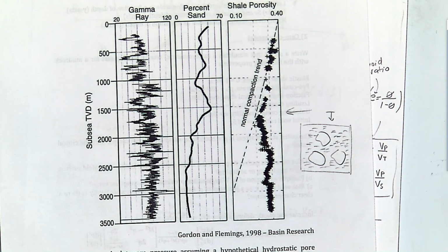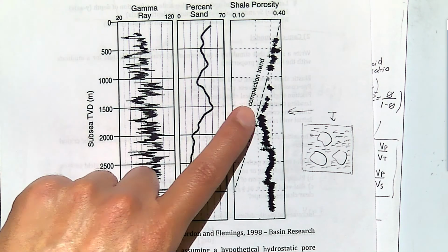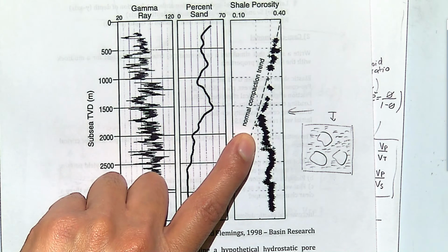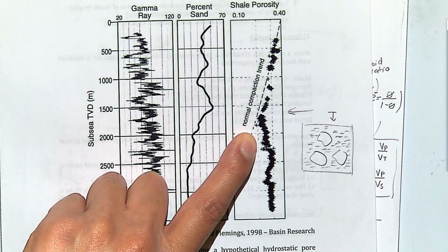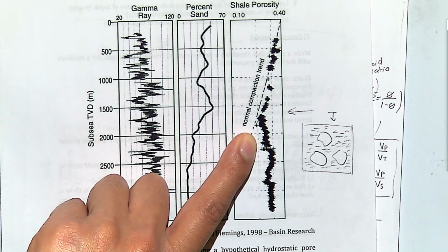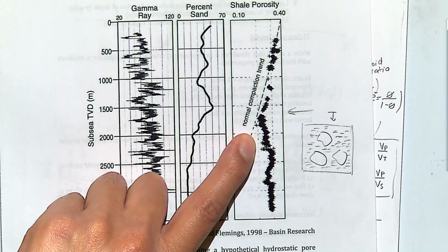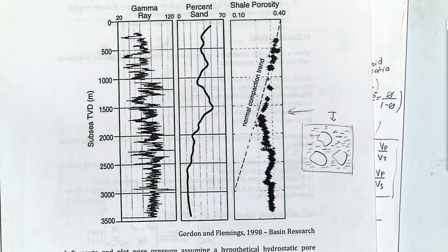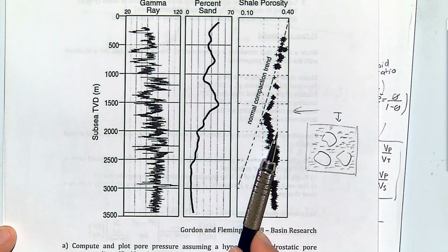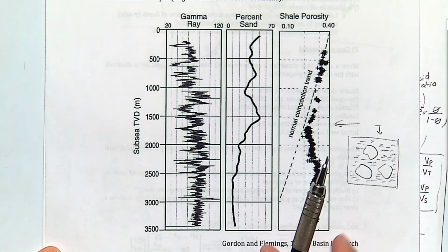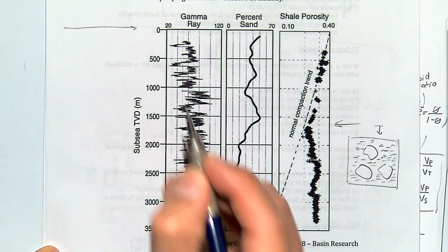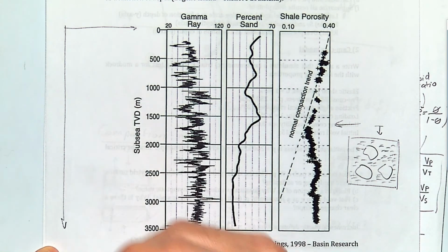Right, so it will be basically up to this point, this is undrained loading, the water cannot escape, and because the water cannot escape, actually the effective stress is not increasing with depth. The vertical stress increases, but the effective stress does not.